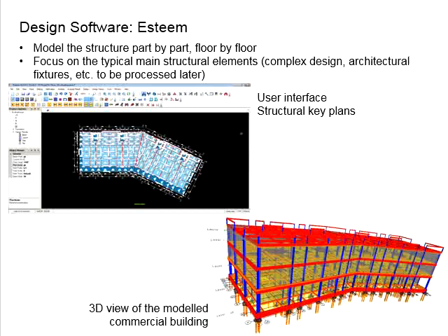This is really good for you to imagine how the structural elements will look based on the key plan that you produce. Is the slab actually sitting on the beam? Are there any misconnections between the structural elements? It even gives you an idea whether the pile foundations will clash into each other if the columns are closely spaced, based on the pile size that you proposed.